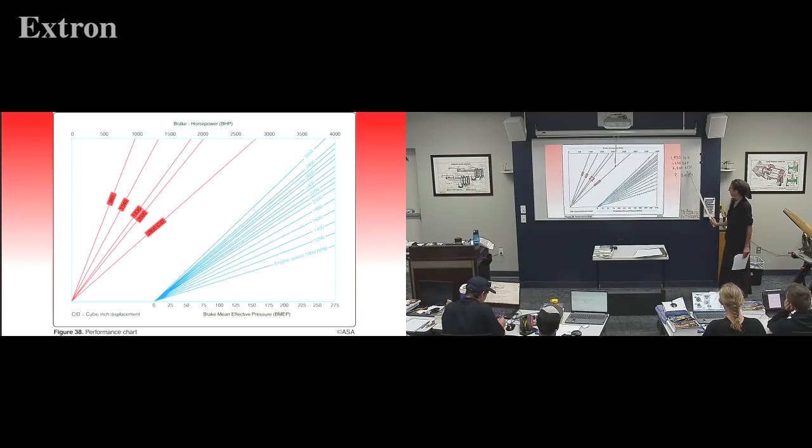Over here, we have engine RPM. So we want the 2,500. There's a line at 2,400, and one at 2,600. So for some of these you kind of have to assume the line in between is halfway, 2,500 RPM. Yes, it's interpolation. So how do you use this chart?